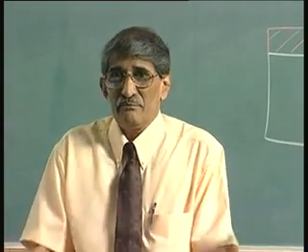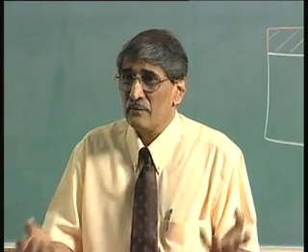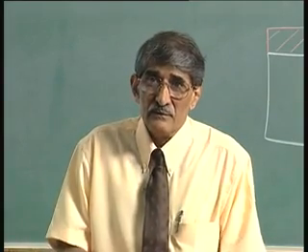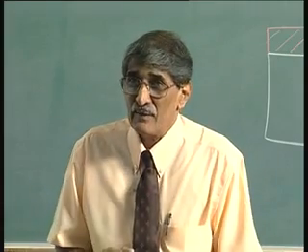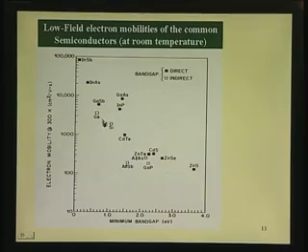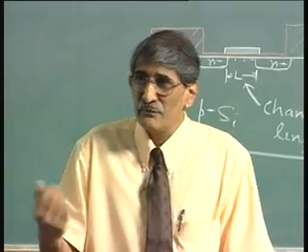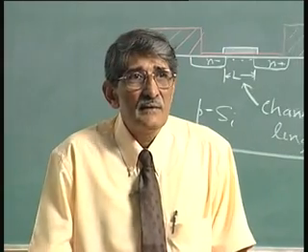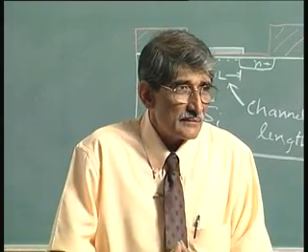So, you have on either side of the fourth group, gallium and arsenic. When you alloy them together into a single crystal material, you get gallium arsenide. Sometimes you call it a 3-5 compound, third group, fifth group. So, gallium arsenide is a 3-5 compound semiconductor.